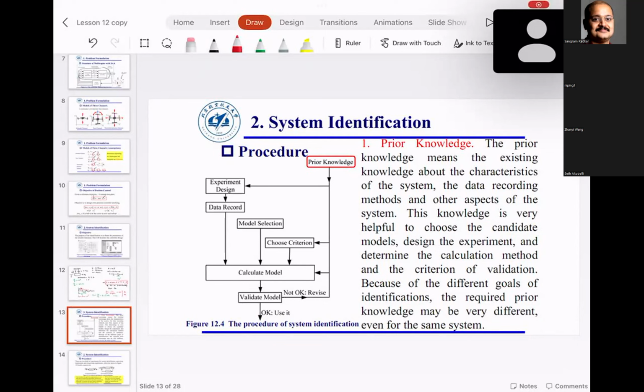From mathematical analysis, you predict the system response to the ramp input. Give the same ramp input to the actual system and see how well the actual response matches the predicted response. And this cycle would continue as long as you have not completed all the scope of operation. So for an example, the system could be subjected to sinusoidal input.